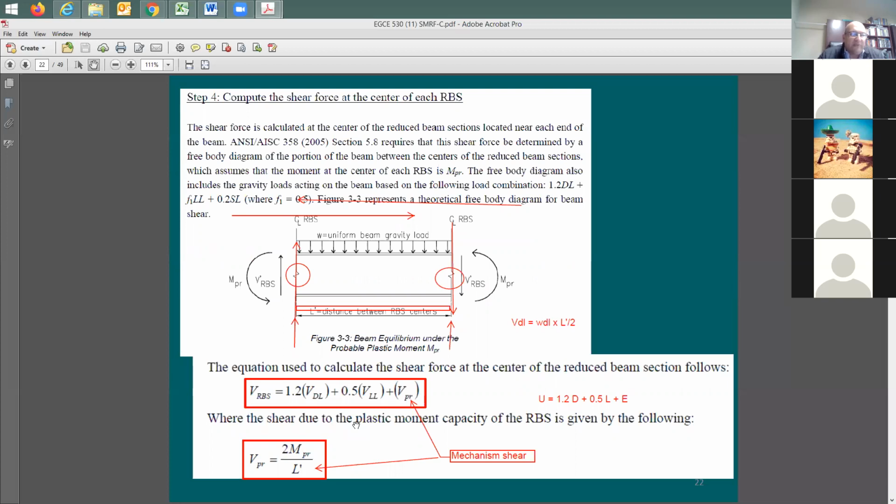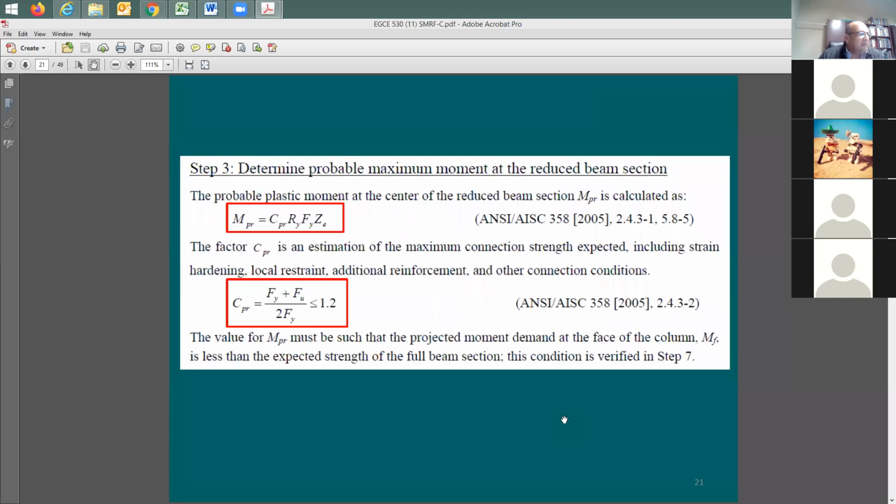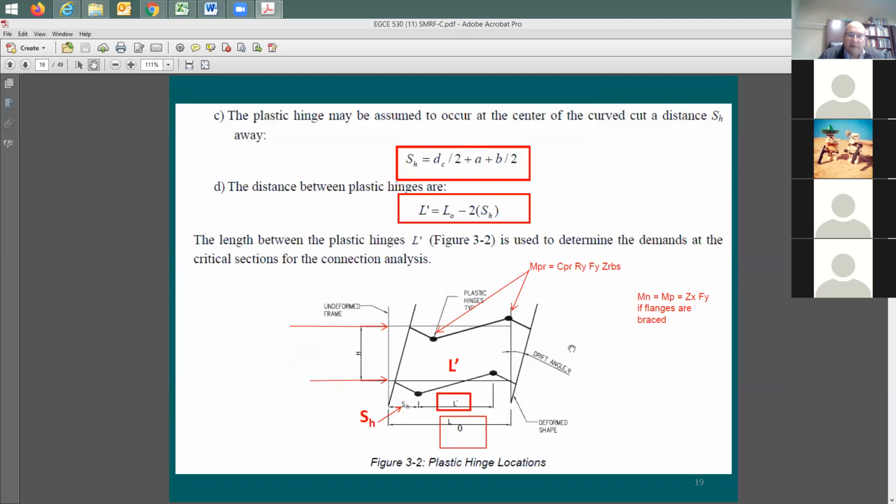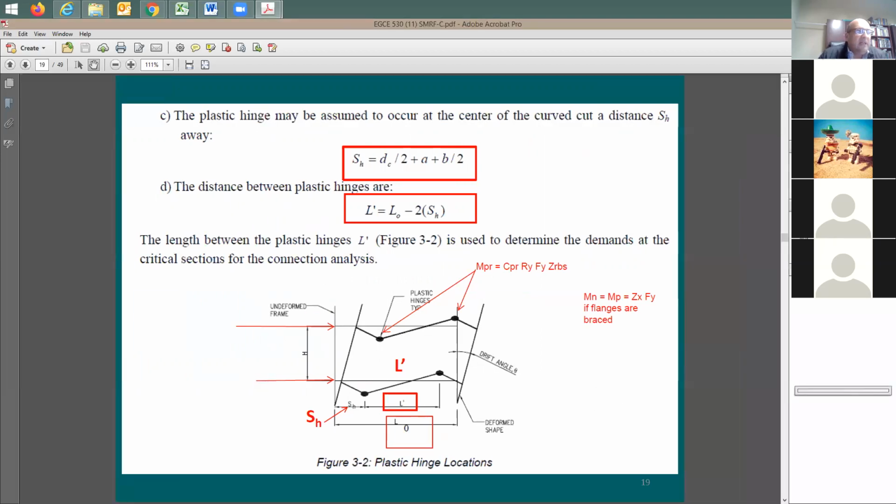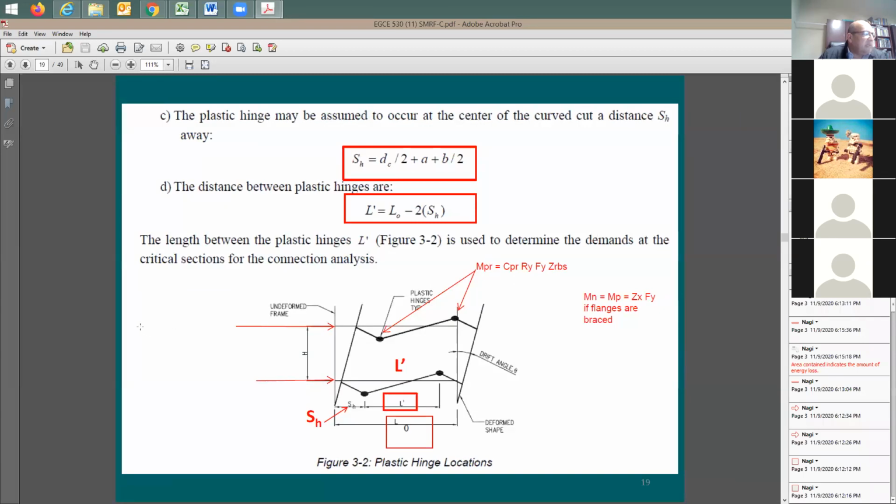At a certain point, the moment frame is going to start to hinge. It's going to start to do something like this. And then after that, you push it, the force is not increasing, the force has now stopped, but you have more deformation because at a certain point we understand that we're going to have this elastic-plastic, or elastoplastic, response. What does elastoplastic mean? Here is the force or the stress, and this gives you the strain on the y-axis. And you guys are aware of this stress-strain diagram. We have something like this.